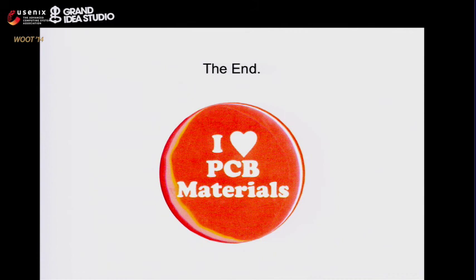Since the layers are glued together, have you tried any chemical solution to delayer the PCBs? Yeah, so there was a bunch of chemicals that I tried to delayer them. None of them worked, which is why none of them were in here. Though there was one that somebody mentioned to me after this work was done. I can't remember the name. Might have been methyl ethyl ketone. That will potentially soften the adhesive enough for you to peel them apart.